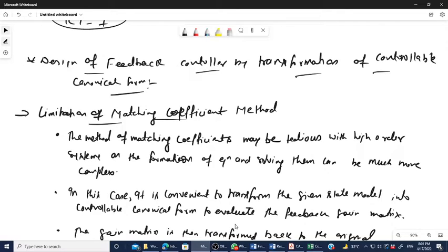Also, we developed the principle of feedback controller design. That is, the dynamics changes when you consider the state variable as feedback, and your dynamics will convert to x dot equals Ax plus B into r minus... that is, to A minus BK plus BF.